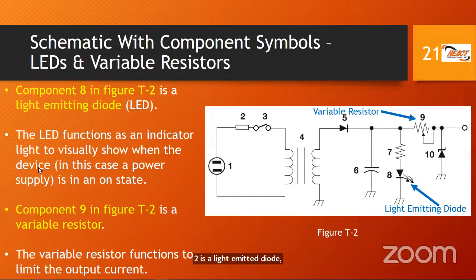Exam question. So just some extra information. Again, this is a power supply circuit. You plug this into the receptacle outlet. You have a fuse, you have a switch, you switch it on, you have a transformer. The transformer converts from one voltage to another, sends it through the diode or rectification stage, filter it out using the capacitor.